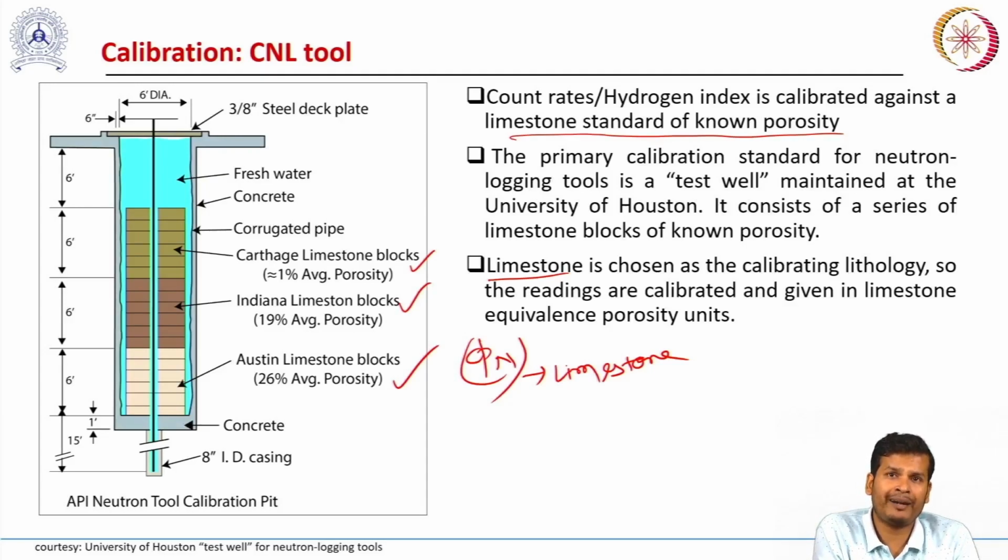Whatever porosity you calculate, if you apply a limestone matrix setting in a wellbore with a limestone formation, you'll be calculating the true porosity of the formation, provided there is no gas or shale effect. So in a liquid filled limestone formation, if I apply the limestone matrix setting, my log data will give us true porosity.